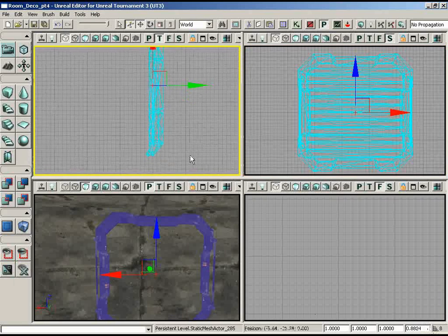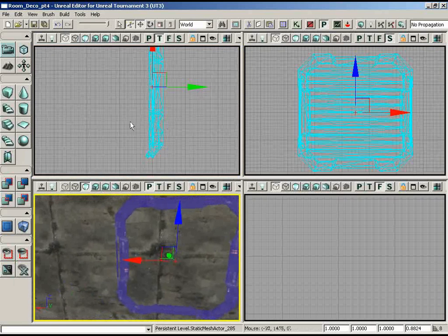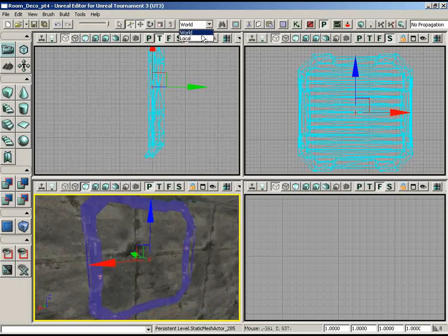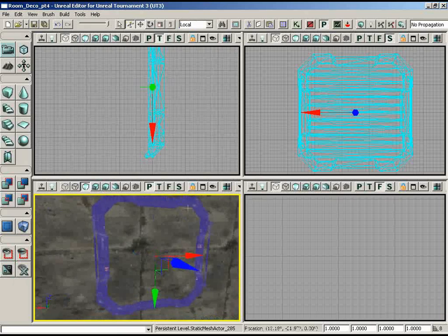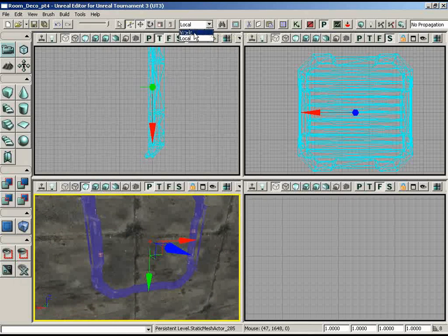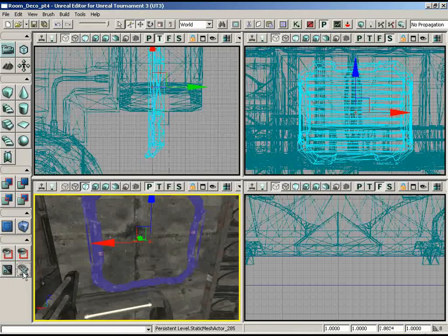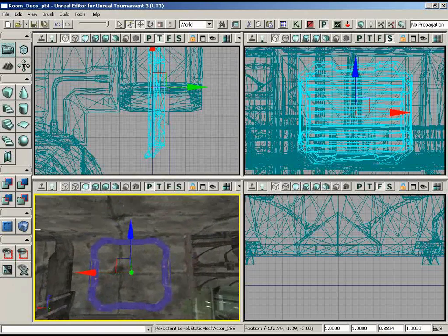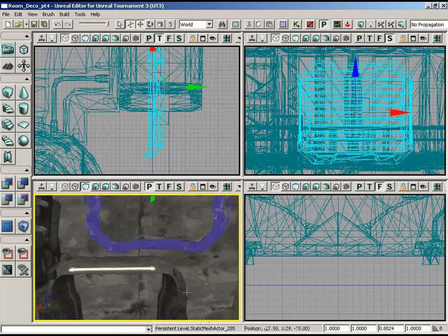And Z is the wrong way. Oh, if you remember, this mesh was supposed to be pointing out at the floor, so we scaled it in on the wrong side. Let's set that back to 1. And let's take a quick peek at its local rotation axis, and we can see there that it's actually Y that we would need to adjust if we want to adjust its height. So we'll plug that number into Y, bring all of our meshes back, move the mesh up just a little bit, and there it centers nicely into the wall, out of the way of the door.